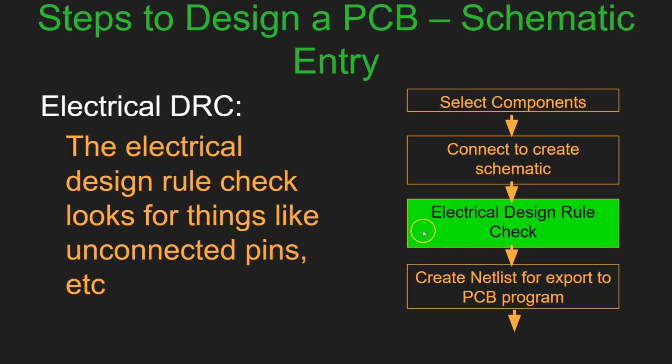And then next, you will do the electrical design rule check. Now, what is an electrical design rule check? It basically involves checking a design for proper contacts and spacings. It ensures correct power and ground connections. Electrical rule check is also a step which can involve checks for unconnected inputs or shorted outputs. It also checks the robustness of a design, both at the schematic and layout levels, against various electronic design rules.